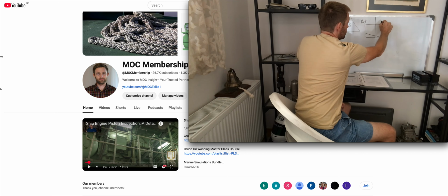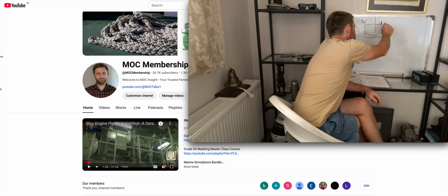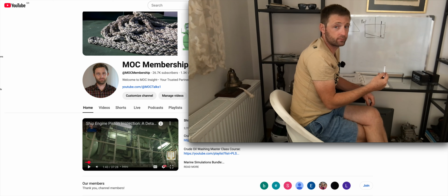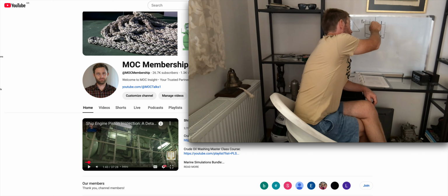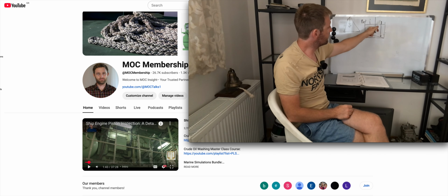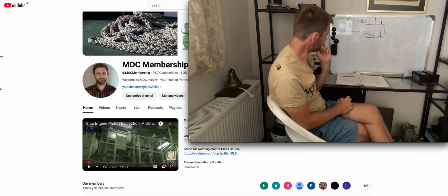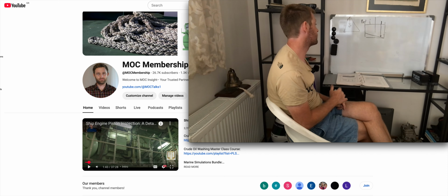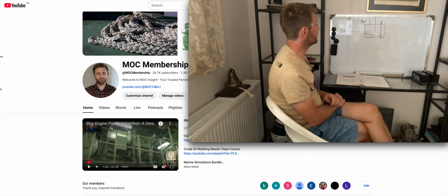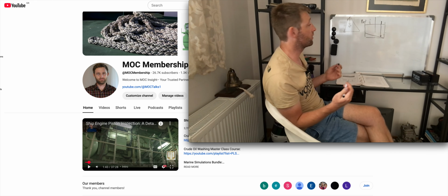So if we have our measuring point here, we also need to determine where the list is. And if we measure the free water, it will not be representative of the quantity for the whole tank, okay? That's why it's very important for modern vessels to have more measuring points in order to identify, or at least a similar measuring point in the opposite location, to be able to reach and measure the product. It can be free water, it can be anything, okay? It can also be ROB at the end.